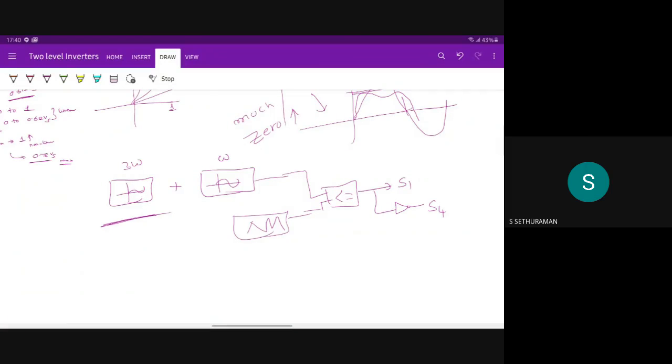If you have doubt on this one, when you are adding zero sequence components, that means A phase modulating signal, B phase modulating signal, VA, VB, and VC modulating signals, if you add all these modulating signals, you must get 0. Then only you have appropriately added the zero sequence. Clear? Any doubts on this?